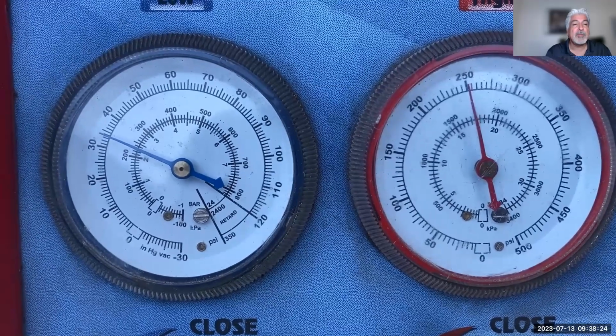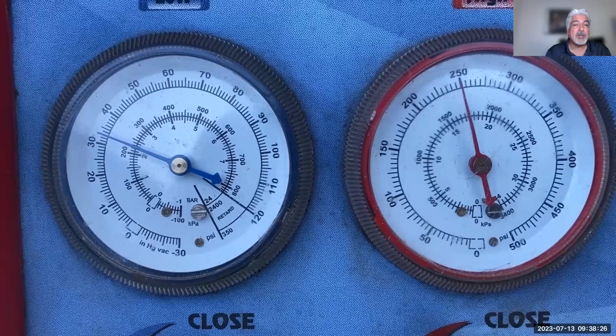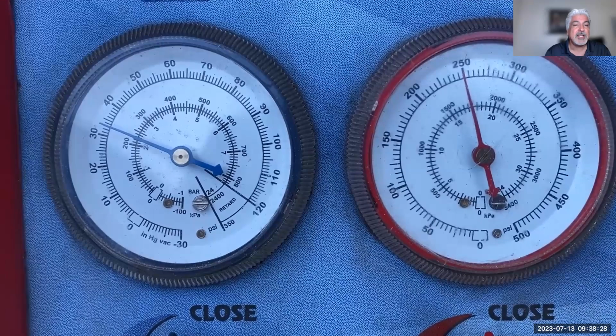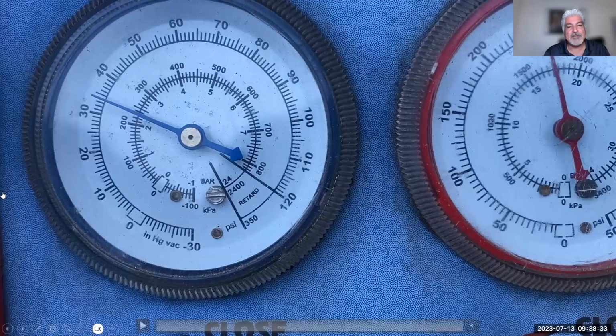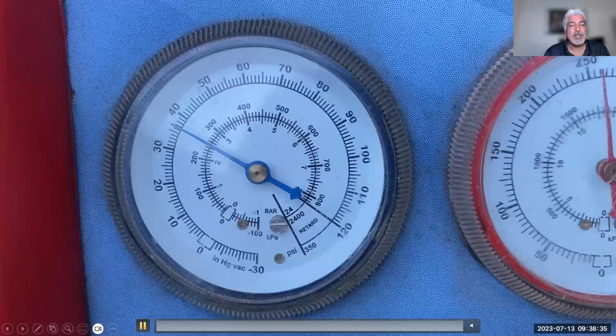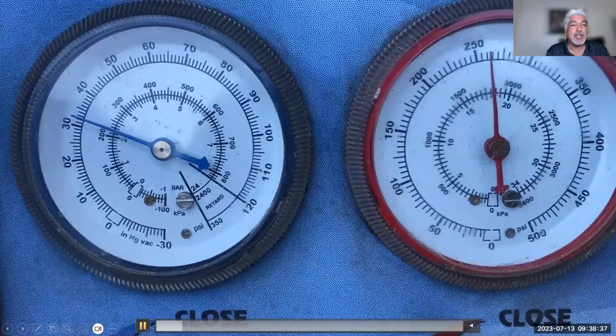What I'm going to show you right there, hopefully this recording is long enough, but you can see it. We're holding at 30 PSI. This is a TXV system. You see the pressure rise, the ball valve closes. The ball valve opens. What happens? This is a perfectly operating TXV valve, by the way. See how the pressure goes up and down? The high side stays steady at 250. That's telling me that the thermostatic expansion valve is opening and closing that ball valve, if you will. So that's normal to see.